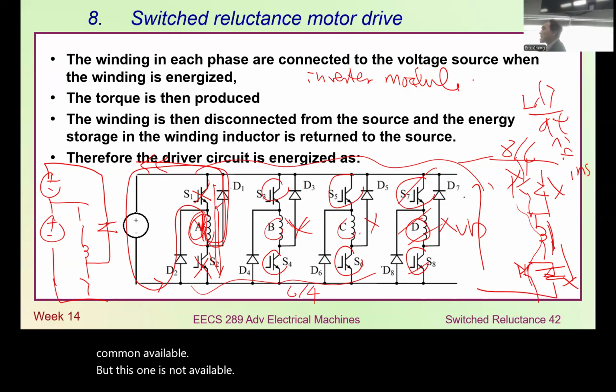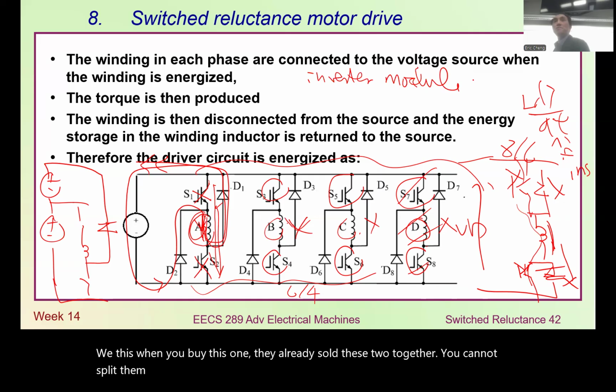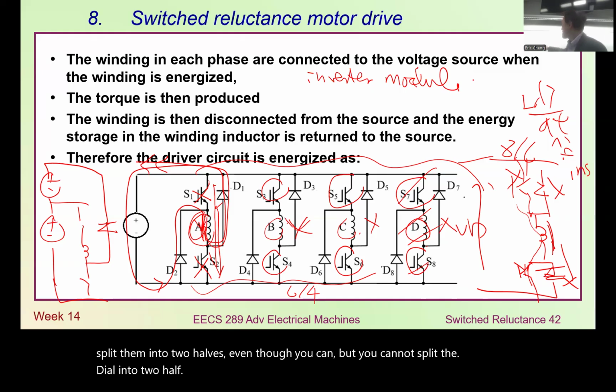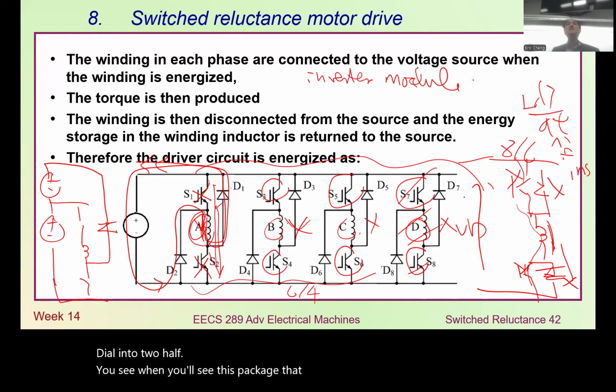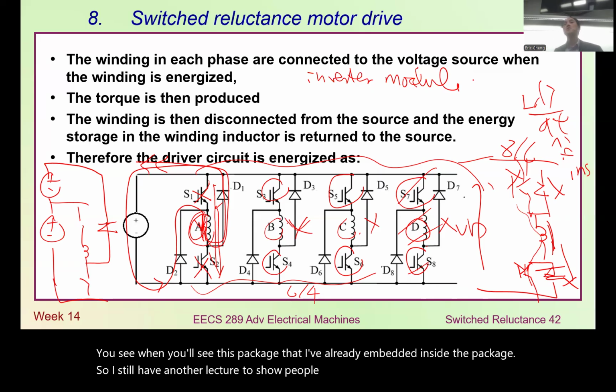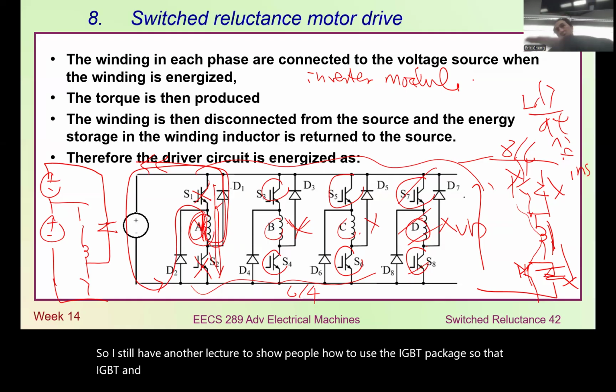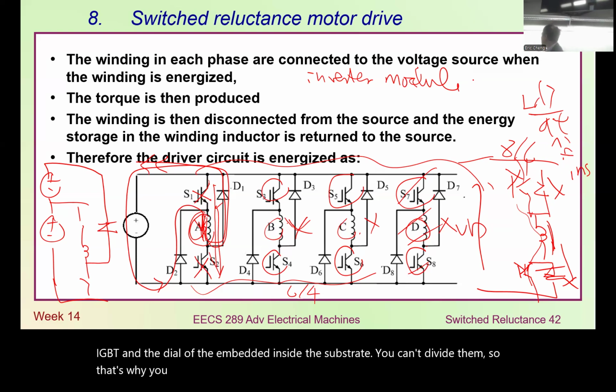When you buy this one, they already solder these two together. You cannot split them into two halves. Even if you could, you cannot split the diode into two halves. When you see this package, the diode is already embedded inside the package. I have another lecture showing how to use the IGBT package. The IGBT and the diode are already embedded inside the substrate. You can't divide them, so you cannot use this kind of motor driver for this purpose.